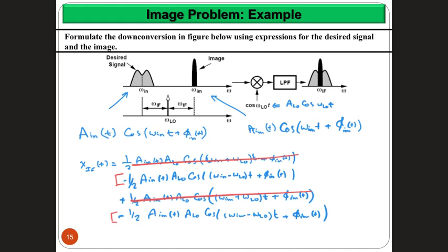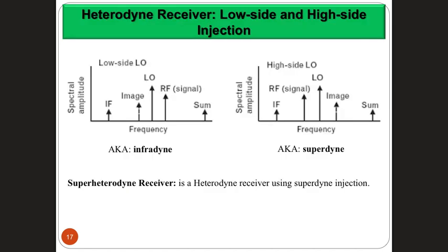That's it for this important note about the heterodyne receiver, and maybe you noticed it when we were discussing the image problem, that I can have the local oscillator below or above my desired signal. In both cases, it's going to bring the signal down to the intermediate frequency, right? With a difference of the sign, positive or negative sign, right?